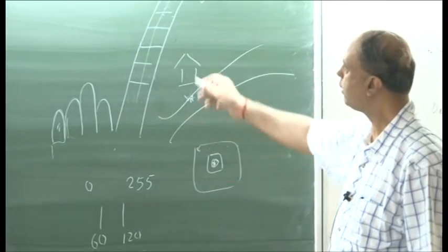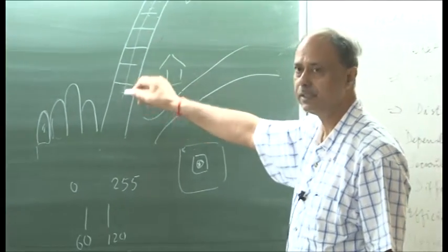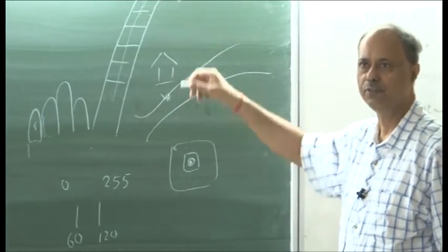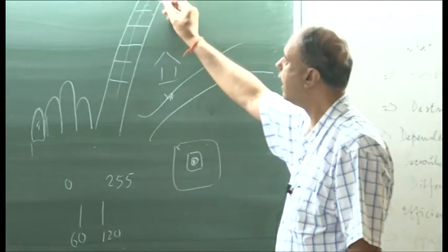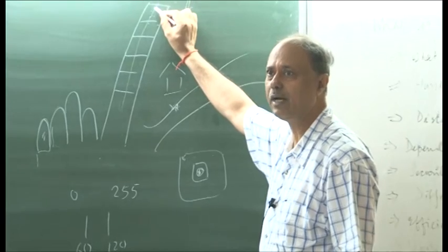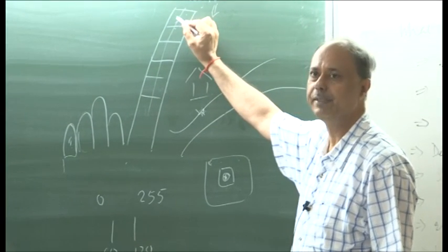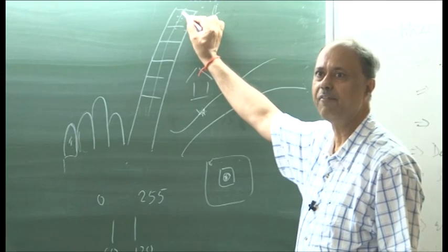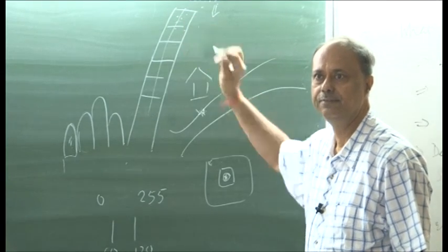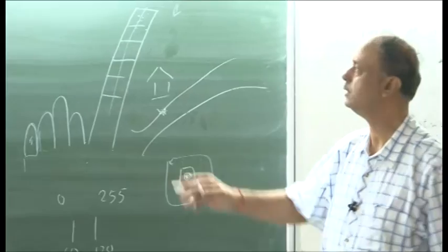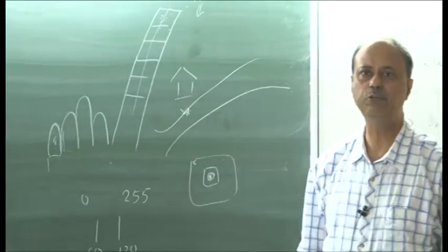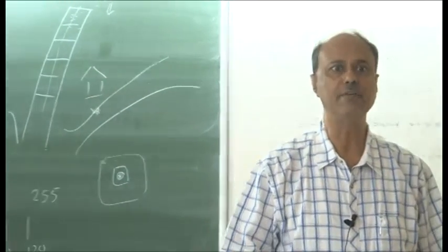So one way, say for example, I have one CCD light that is off. Now I have to estimate this value. What will I take? I will take the behavior of the two neighboring pixels and put an average value here, right? So the behavior of these two has been taken into account, and I get the smoothing effect.